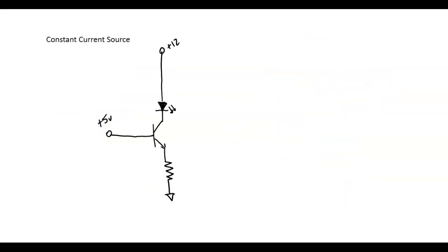Okay, so this is another thing I wanted to show y'all. We talked about constant current source. So I'm going to put 5 volts over here, and I'm going to say about 1.5 volts at 15 milliamps. So I'm going to come over here. This is going to put approximately 4.7 volts right there. Everybody understand that? So what size resistor would I need to get 15 milliamps to drop 4.75 volts?